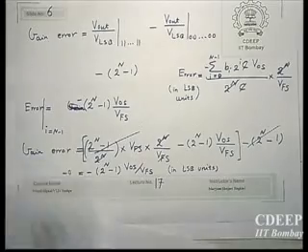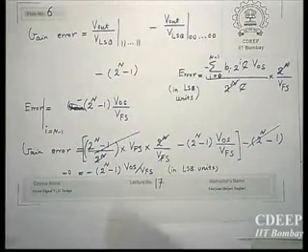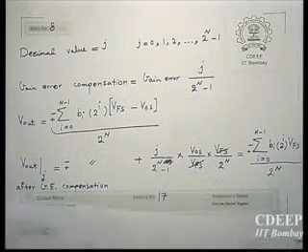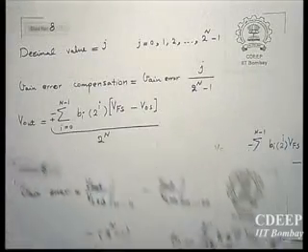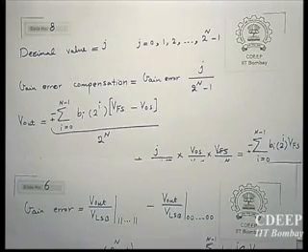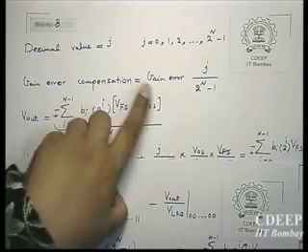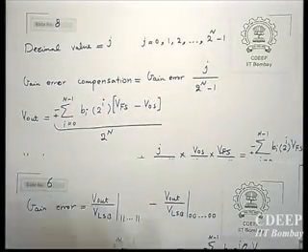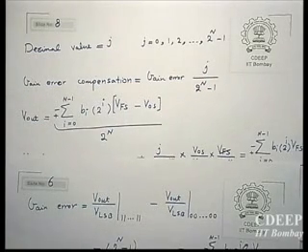And then I wrote it versus the decimal values like here. Okay, now gain error was this term, V offset upon V full scale, 2 to the power n minus 1. And then gain error compensation is the value of decimal j upon 2 to the power n minus 1 into gain error. Am I correct?